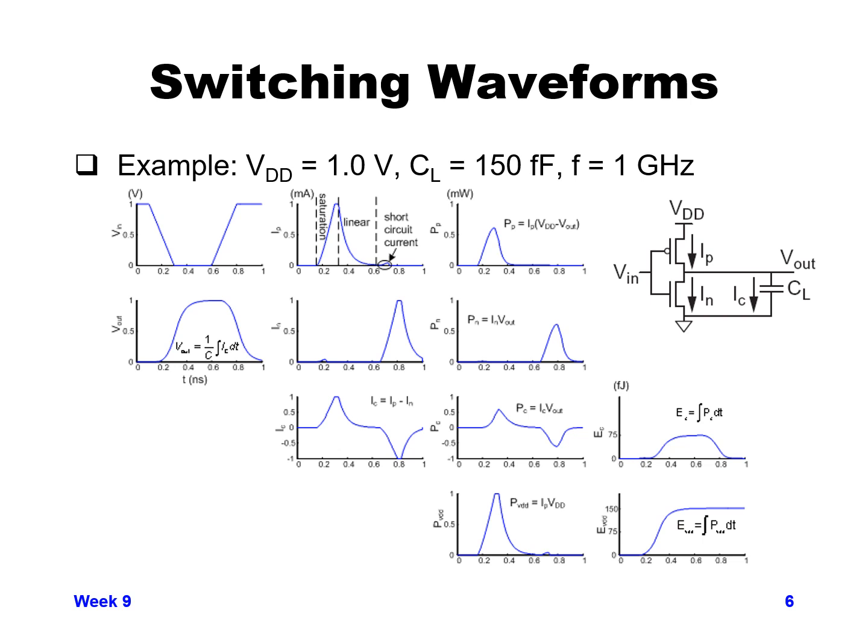And then there's a little bit of short circuit current, as when the input switches back from ground to VDD, it turns on the NMOS device to start discharging the capacitor. So you can see the second curve from the left, and the second one down, is the current going through the NMOS.